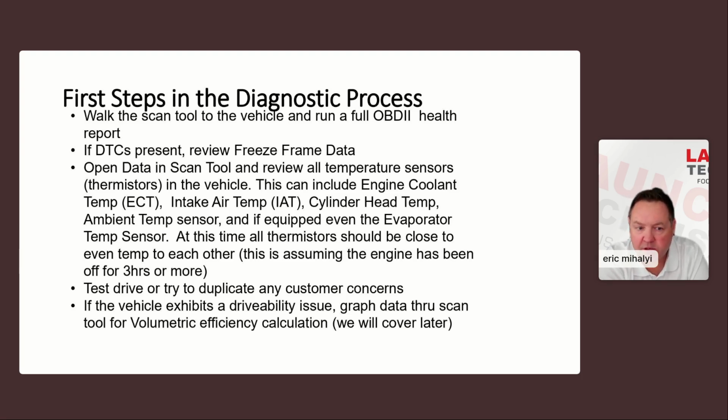And the reason why I do that without the car running, and this is also assuming the engine has been off for 3 hours or more, which is usually a condition I request before I look at any car for a drivability issue, is you need to drop it with me, whether you drop it the night before or early in the morning, so that I can let it sit and look at the car cold, if you will, right? So that as long as it's been off about 3 hours or more, all those temp sensors should be about even, right? ECT, IAT, cylinder head temperature.